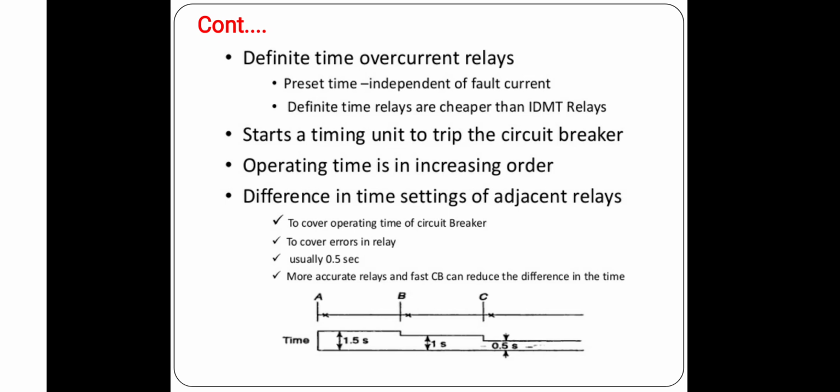It means that the fault current is practically the same if a fault occurs on any section of the feeder. This is true for a system in which the source impedance is more than the impedance of the protected section.